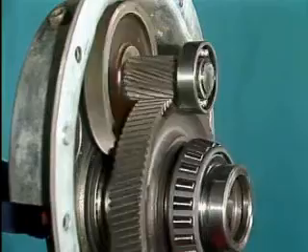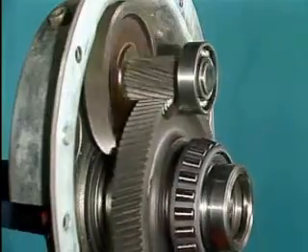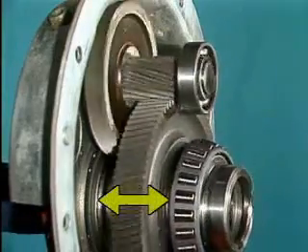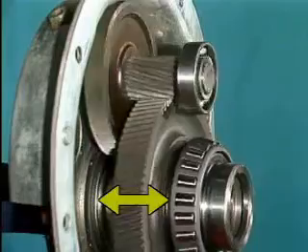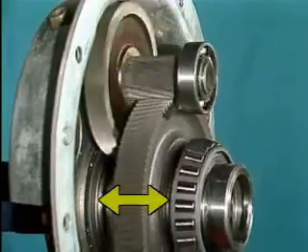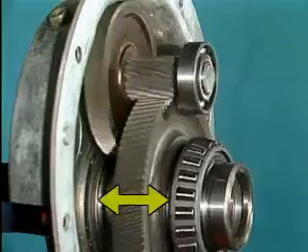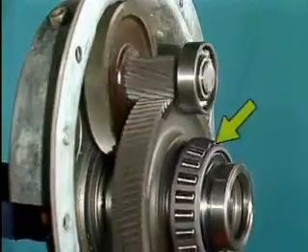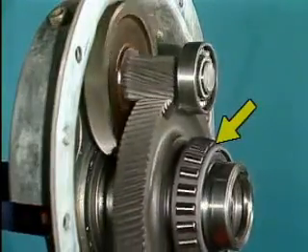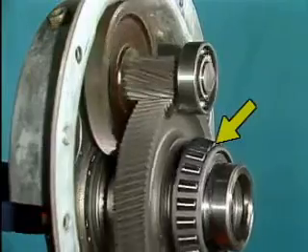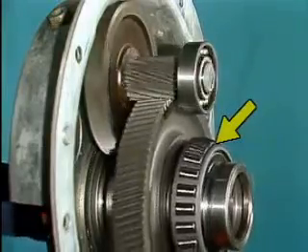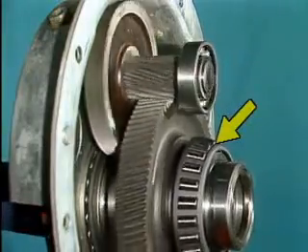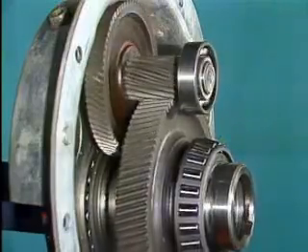Unfortunately, however, there is a problem associated with helical gears that needs to be addressed when these gears are used. The problem is that as helical gear teeth mesh, an axial thrust is developed along the shafts that support the gears. In other words, the gear and shaft try to move sideways. One of the ways to compensate for this thrust is to add a thrust bearing on the gear shaft. A thrust bearing absorbs axial thrust and holds the gear and shaft in the proper position inside a gearbox.